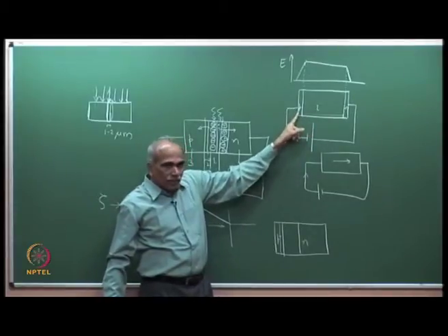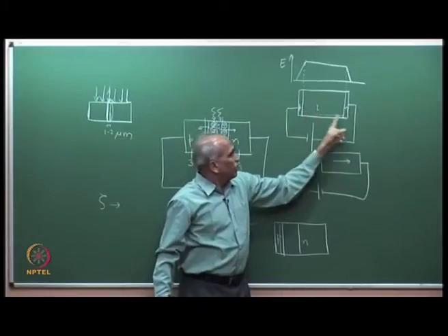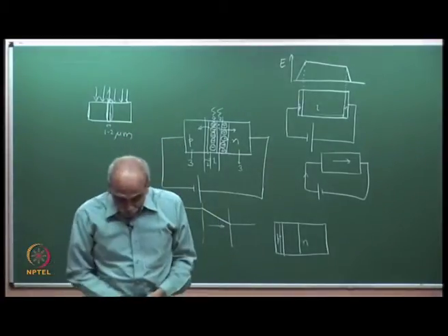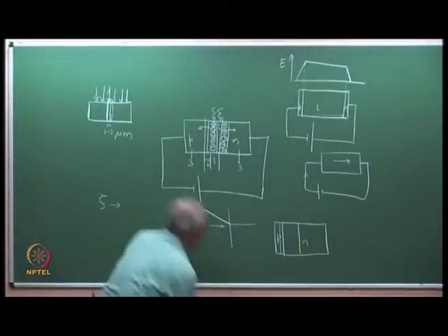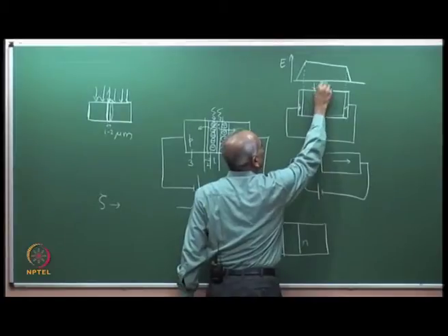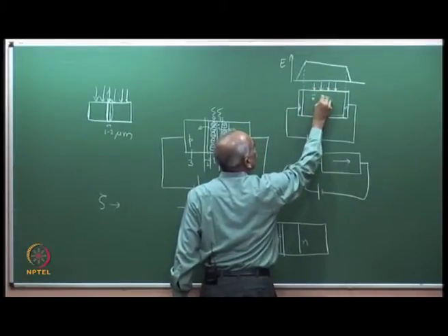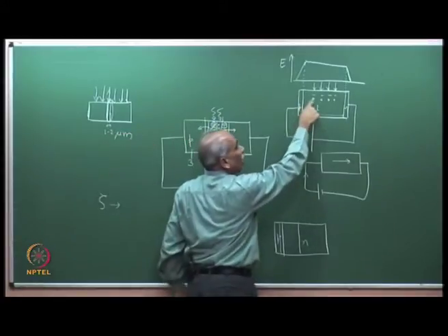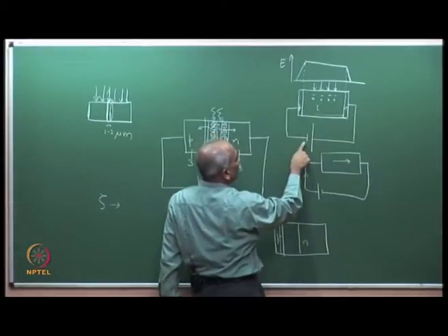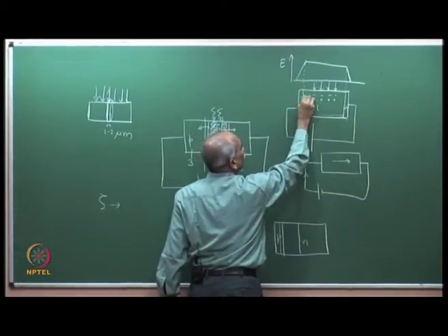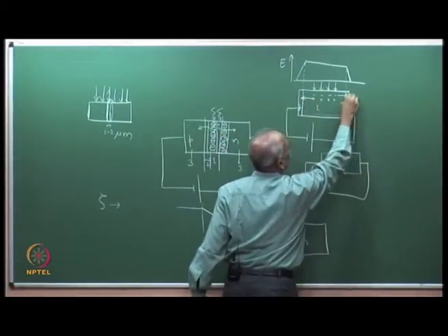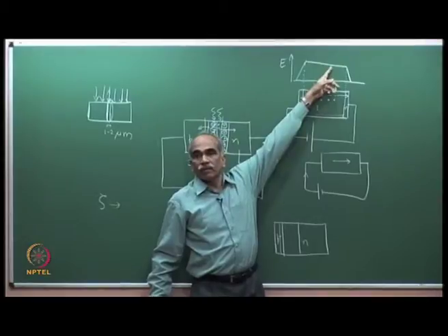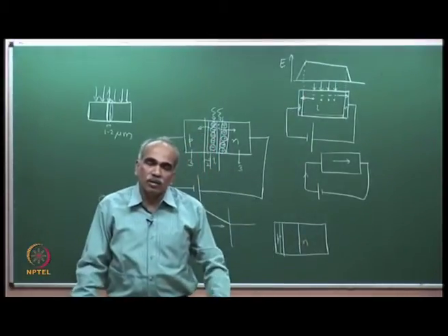When you have a high doped P region and an N region here and very lightly doped this one, the entire intrinsic region becomes like a depleted region. And therefore, now the area of capture is very high. Light which is incident in this region, all of these will create electron hole pairs. It was creating even here, but they are under an applied field, and therefore immediately this end is negative. So, the holes immediately rush to this side and electrons rush to this side. The carriers are drifting apart very rapidly, because there is a strong electric field here. The carriers are swept in opposite directions very rapidly.